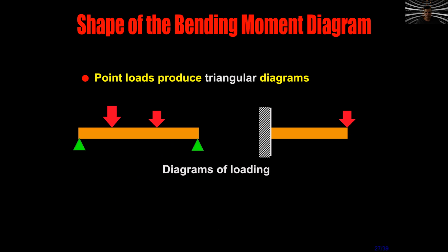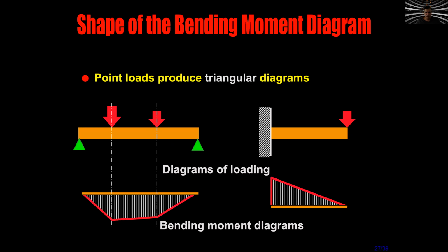This is a beam, and the load will be like this. In the cantilever it will be different. I mean, the moment will be zero near the force, and after will grow. But as I explained to you, we will not study cantilevers. In this review, we are studying only beams that are supported at the ends, that are the normal usual beams.